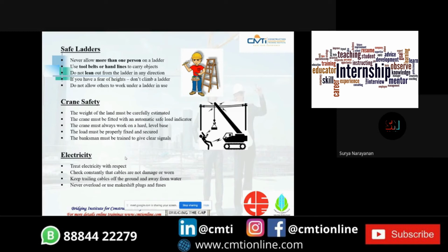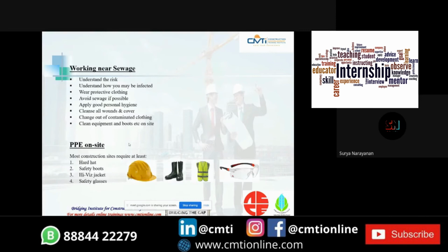Electricity should be treated with respect. Any damages or wounds to equipment should be corrected during construction. Keep trailing cables off the ground and away from water. Never overload or use makeshift plugs and fuses.